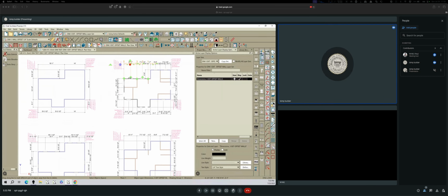Or you have to add these things up in your head to locate that wall. If you got your tape measure hooked there and you're pulling it down this wall, yes, you can mark the first window. But now you have to either move your tape to the center line there, or you have to add these two dimensions in your head to get that location.